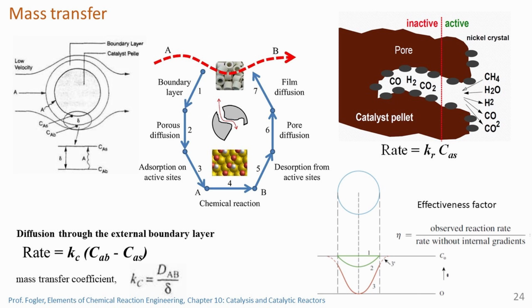However, when a chemical reaction occurs on a surface, the rate of mass transfer to the reactive surface is in steady state and equal to the rate of reaction. If diffusion or mass transfer steps are very fast, there is no resistance for the mass transfer from the bulk to the particle surface and from the particle surface to the active site in the pore.